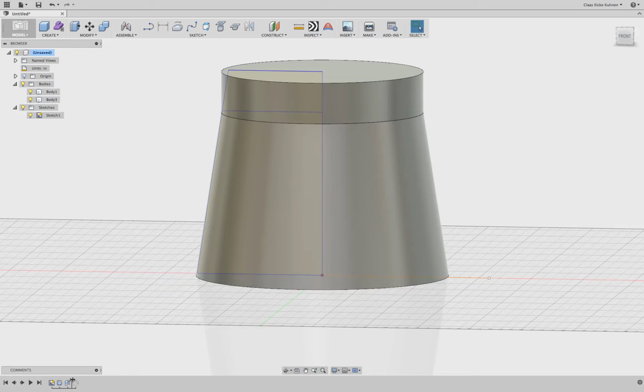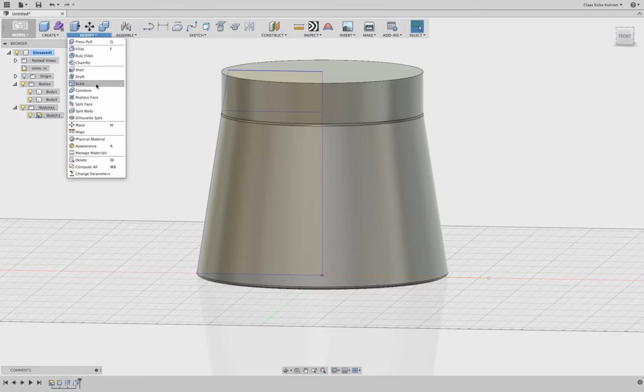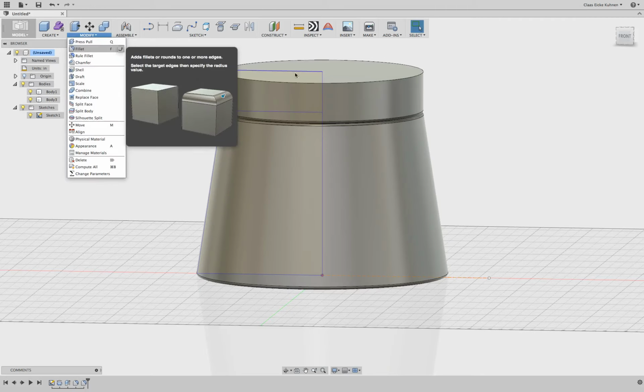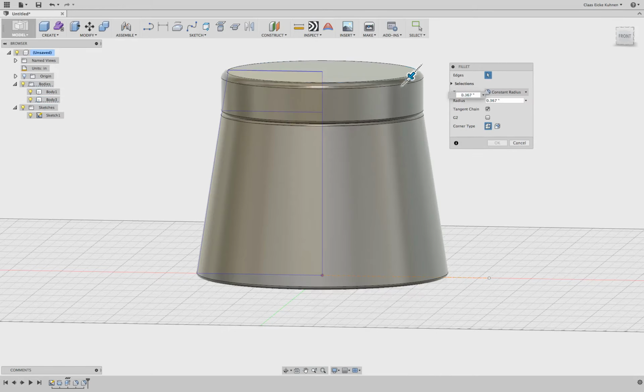And you see now when I go back time-wise, my base is filleted again, but not the pillow. And then I could, for example, go back and say fillet, you also please 1/4 inch. Okay, and then one more time up here and round this one down.